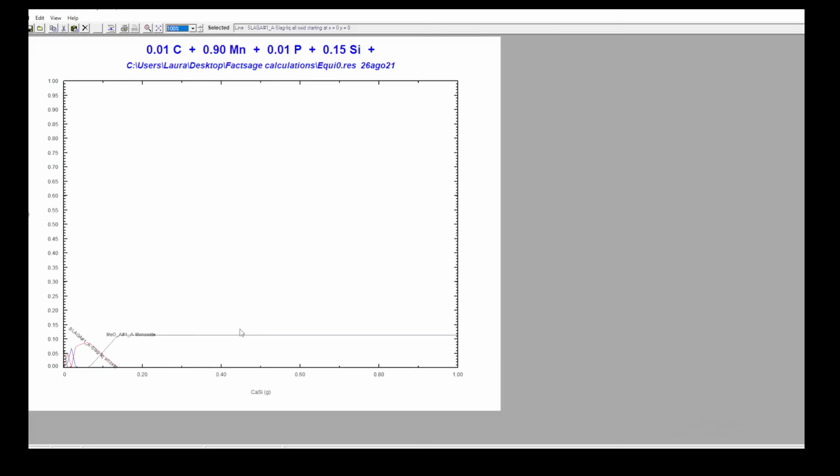So now, with the proportion that we are using of aluminum and calcium silicon, we do not form a single phase. So we need to optimize the aluminum to calcium silicon ratio. So maybe we can remove that and just form the slag. So in this example, the deoxidizer is not working perfectly. We need to adjust this proportion and pay attention while we are doing this addition, to make sure that we don't add too much calcium silicon, because then we would be forming solid.